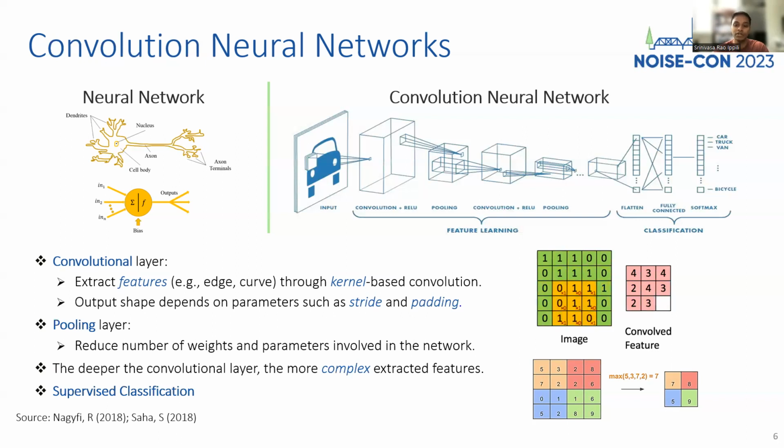Here, we input the flattened feature outputs to a classifier for final classification. CNNs can use either transformed vibroacoustic data or sometimes raw time series data for fault classification, thereby eliminating the need for human expertise on feature extraction, thus saving time and computational resources at the same time.